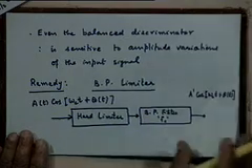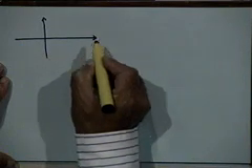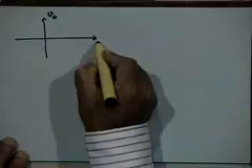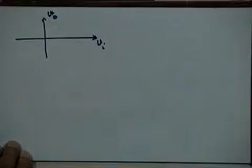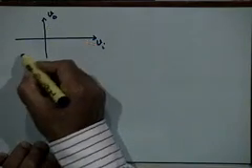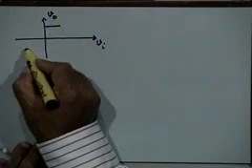It is fairly simple theory, but let us go through it, because it is important to have a very clear feel for these things. Let us start with the hard limiter. Hard limiter is a device, as I mentioned earlier, something like a highly saturated amplifier, or you could say it is a clipping circuit which clips at 0, right. So, if you were to plot the output versus input characteristics, output voltage versus input voltage on an instantaneous basis, then for an amplifier it is a straight line passing through the origin, right. For a hard limiter it is a highly nonlinear system.